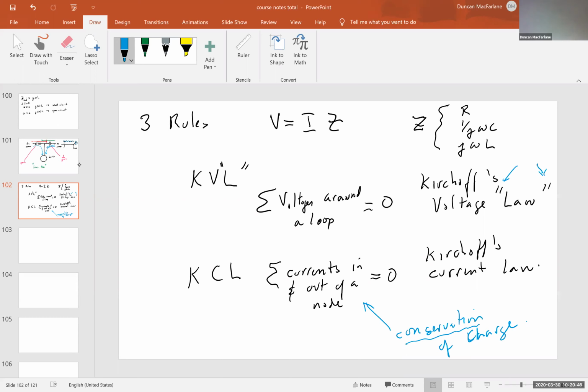And so charge is just a property that's in addition to energy. That's a great question. So I'm being kind of formal and rigorous when I put these little quotes around the law. It's only a law at low frequencies. Kirchhoff's voltage law is a law only in the sense that you're doing circuit theory, the approximation of circuits.